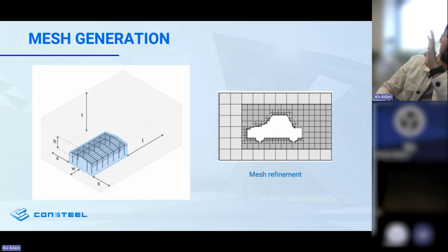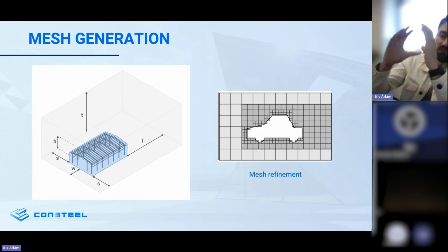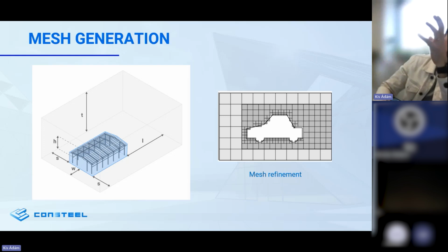Let's say it is 8 meters. And with every refinement step, these cells are divided by 2 in space. So from a block of 8 by 8 by 8 we get a few 4 by 4 by 4 cells, and so on, until we get a precise mesh size on our structure.